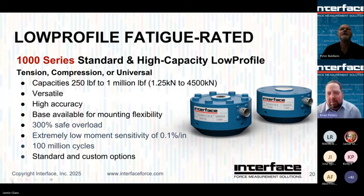So our most popular fatigue rated solution is going to be our 1000 series. This is based on our very popular and very reliable low profile family. These capacities start at 250 pounds and go up to a million pounds force. Very versatile, very rugged, very high rejection to side loads and eccentric loads, which are very critical for fatigue. We'll mention that in a minute here. Very high accuracy, and of course, bases are offered and always encouraged. Please, if you buy a low profile, get it with a base. But these do offer very high safe overload as well.